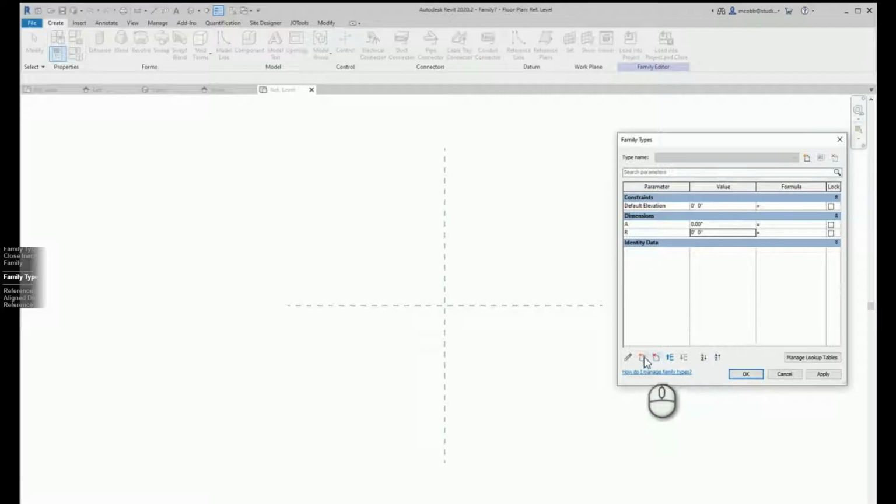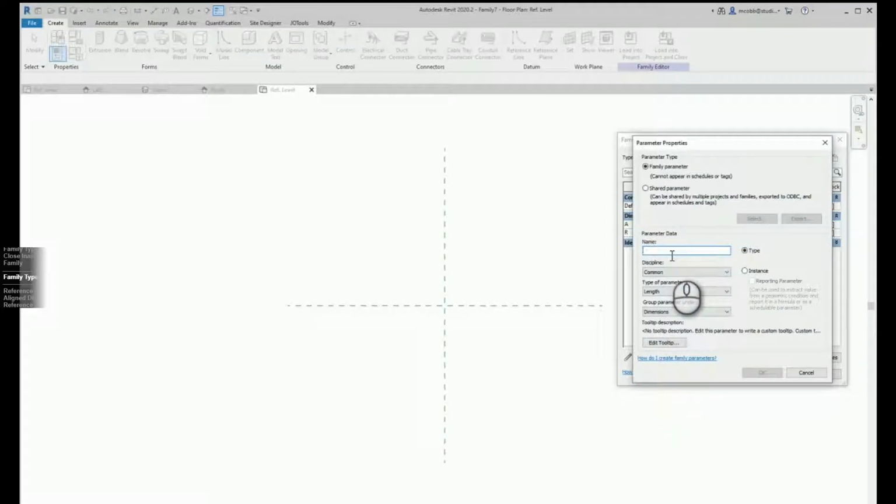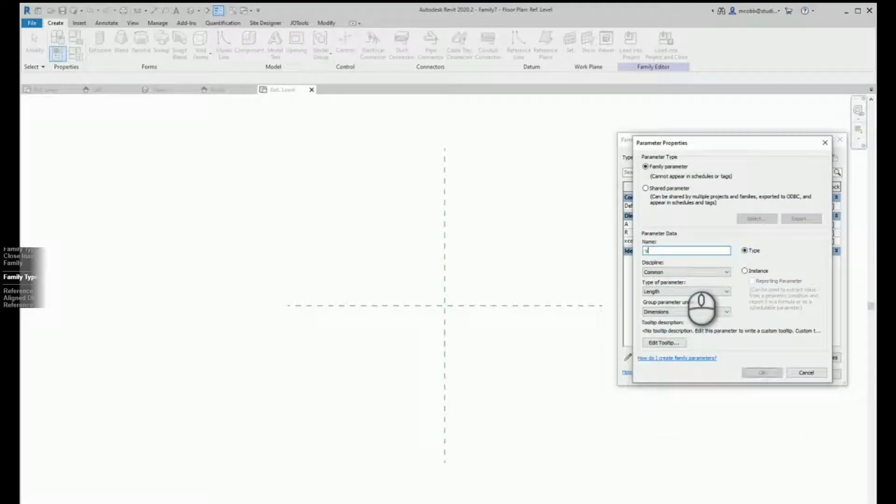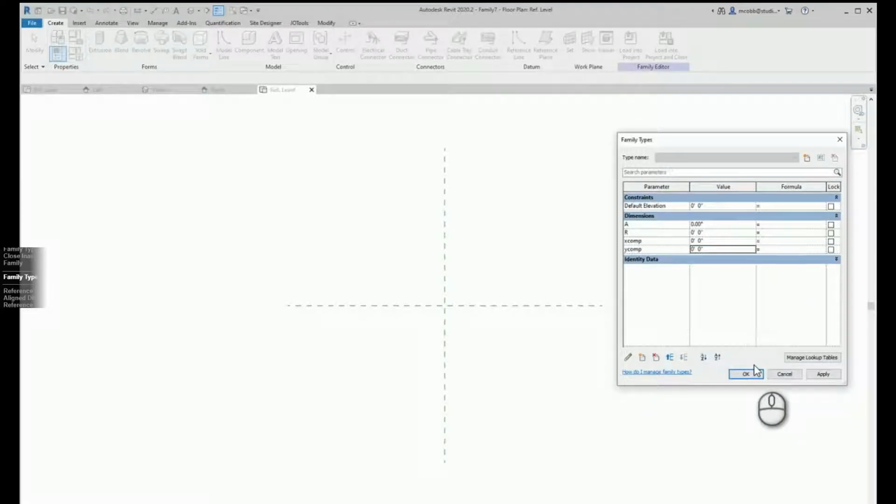In addition to that, we are going to create two other parameters, an X component parameter and a Y component parameter. This was my recollection of my early trigonometry lessons, and I thought that I was going to basically create an X component and Y component, have a reference line essentially snap to the intersections of some reference planes, and circumvent this issue.